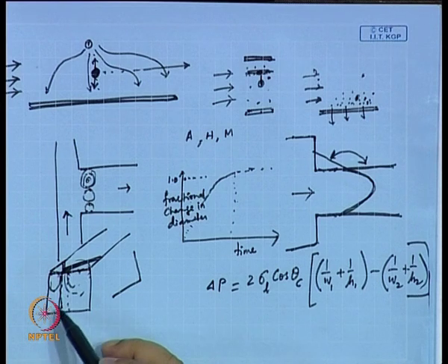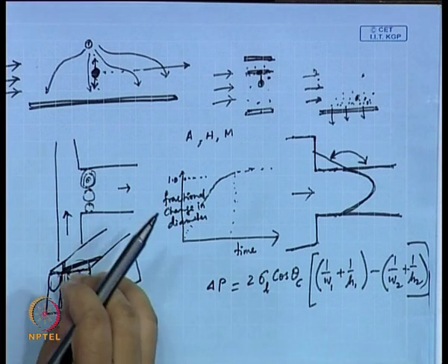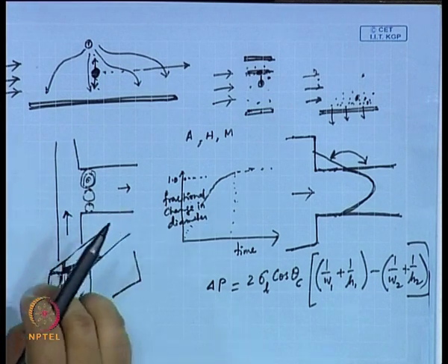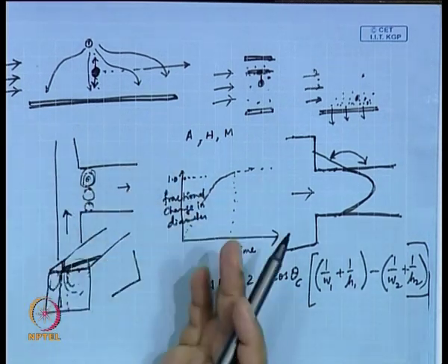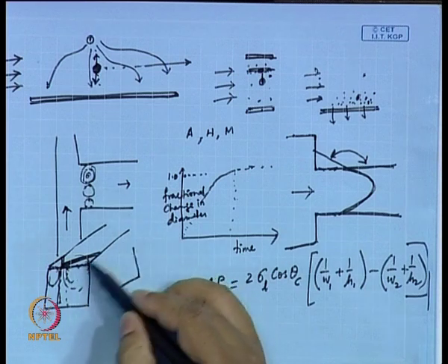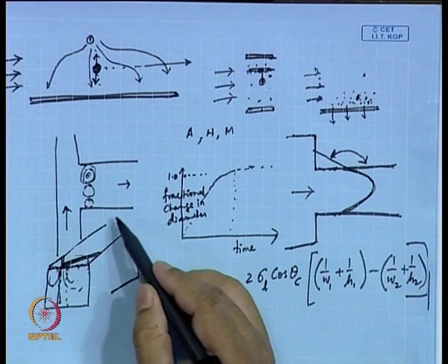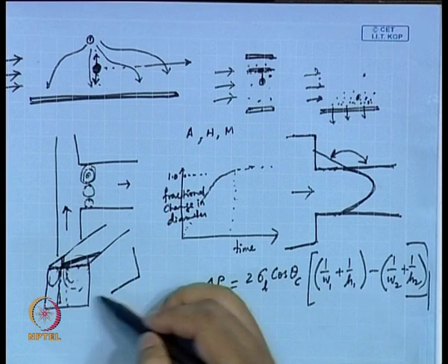However, you started working with 2/3 on this side and 1/3. So, you picked up a certain portion from this and you are putting it into the other stream, and after the 5 such grooves, you are reversing the flow pattern. By this way you are having cross flow, then again moving in the other direction. At the end of it you are accomplishing a thorough mixing, that is the whole idea.